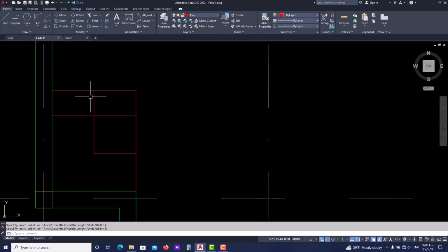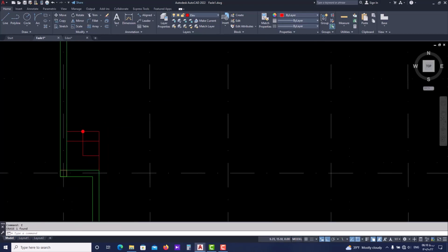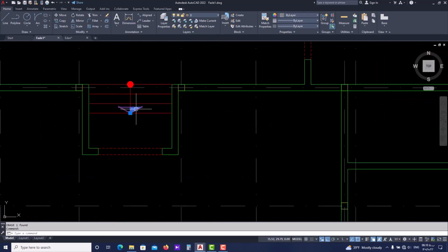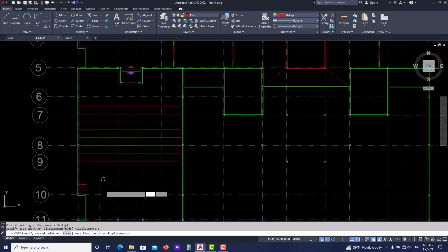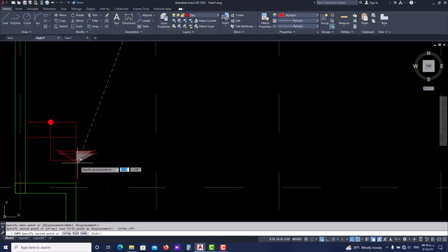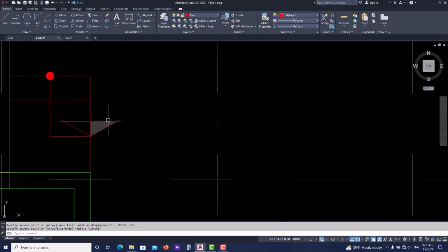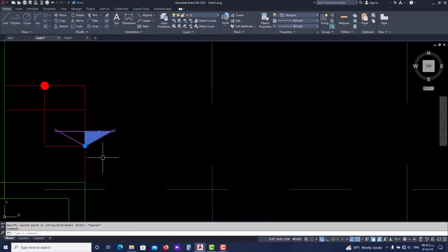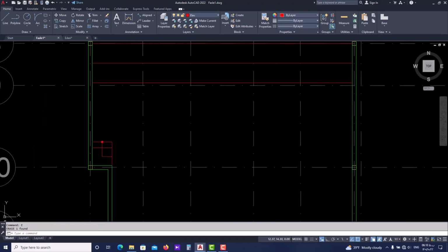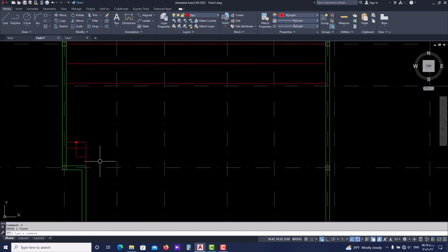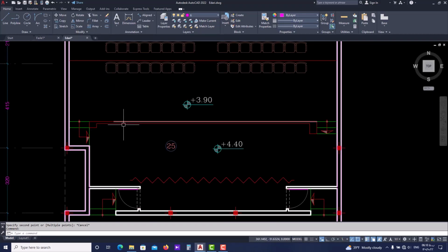Now what technique did we say we can use here? Exactly, donut. DO enter. So first diameter 0. The second one we can put at 0.2. It's kind of large. Again 0 and 0.1. Yeah, this is good. Okay, now for the arrow, we can use the arrow up here. We can copy it. But there's a point here. If we copy the symbol down here, we need to rotate it, and we haven't learned completely how we can use rotate. So for now, we can just leave it.